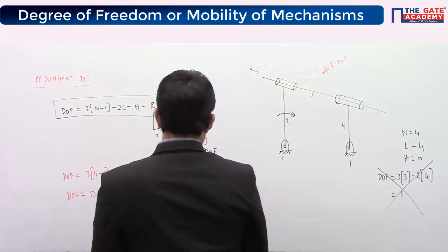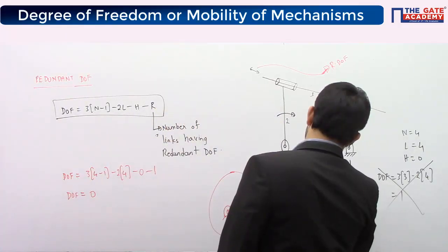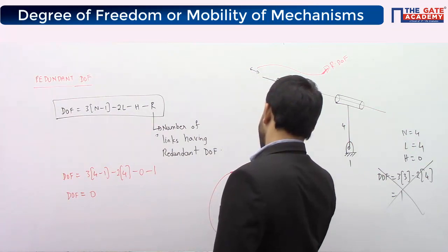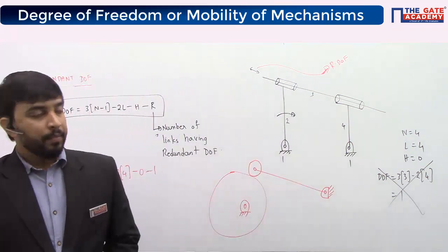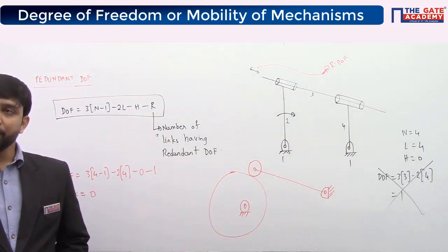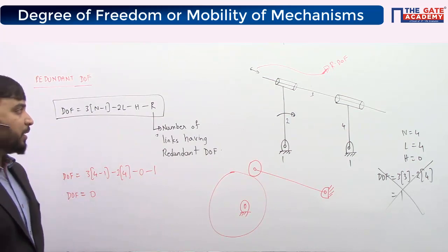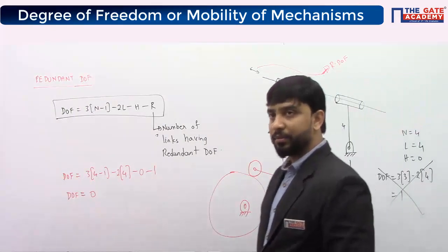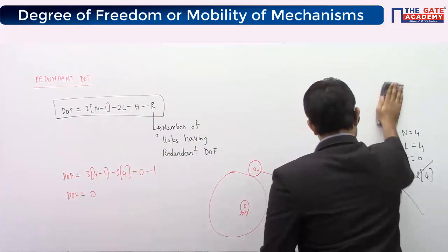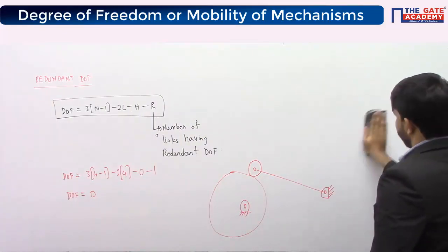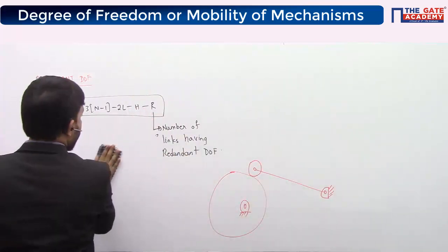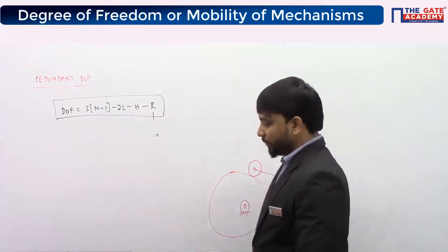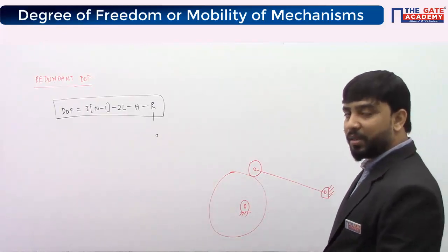Okay. Try to solve this problem. Gruebler. Link 3 is having redundant degree of freedom. I can move link 3 without giving motion to other links. So what's the answer for this? If you look at this mechanism, in this mechanism there is one redundant degree of freedom, okay?